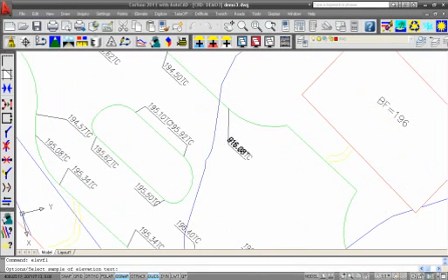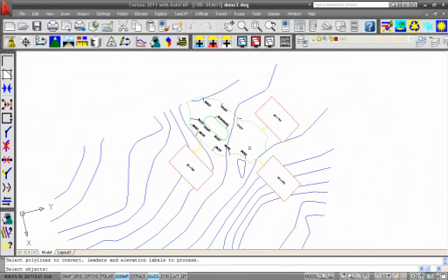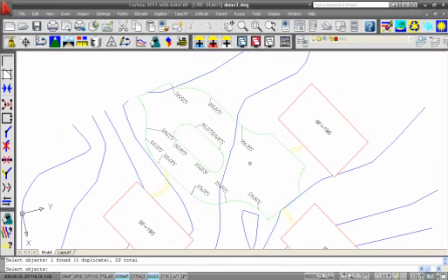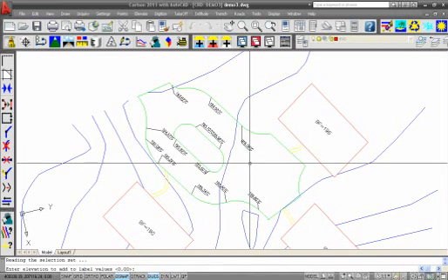So by text with leader, you're familiar with this command: select the text, select the leader line, polyline to convert. What to process, do a window, and do a window this way, around these. Got all my line work highlighted there that I want to use, hit enter.